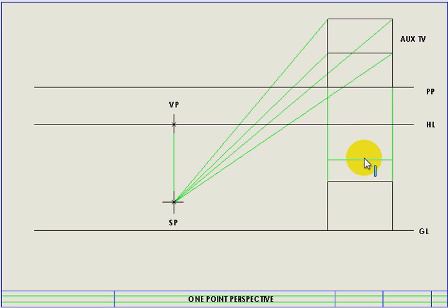So remember that this roof top line over here is actually this line over here, which means I've got a point from this bottom point over here slanting away from me to the top of the roof, the apex, the very top. There I have my ground line, sorry, not my ground line, my picture plane, and I'll be going to move away from my picture plane to find the top of the roof. So let's go and connect each one of these points for my roof.